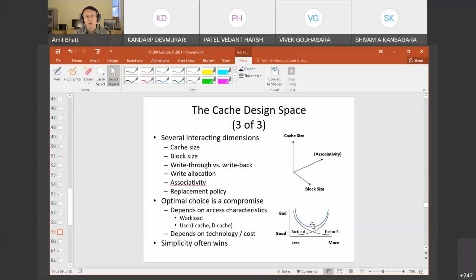And it all depends on cache hit or cache miss, or how many times it has to go all the way to main memory. So if you want a guarantee, or you want to have surety that my program would execute within this much amount of time, then you have something which is known as TCM, or tightly coupled memory. So that is just one level of memory. There is no hierarchy. And then, it is easy to determine how much time the execution of the program would take, which is the requirement of a real-time system.